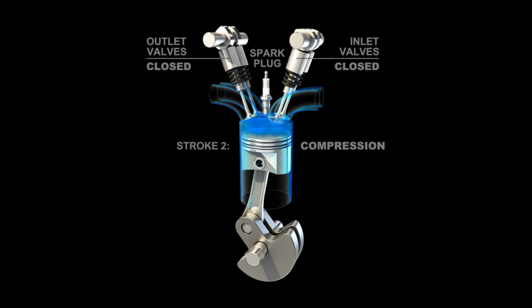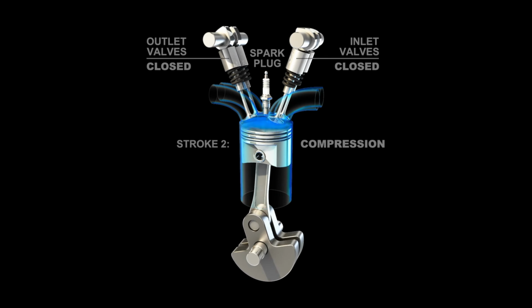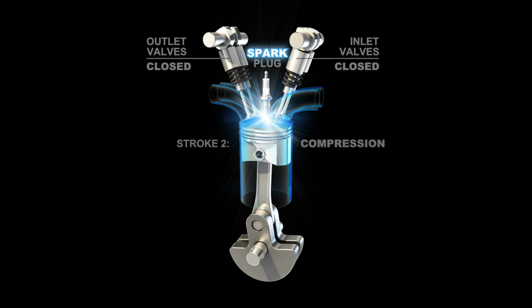Now, somewhere between the point where it's traveling upwards to the point where it reaches the top of its travel, known as top dead center, we're going to typically fire our spark plug off somewhere in that particular range. Now in this example, we can see here, once the piston is almost at top dead center, that's going to be where the spark event is commanded in this example.